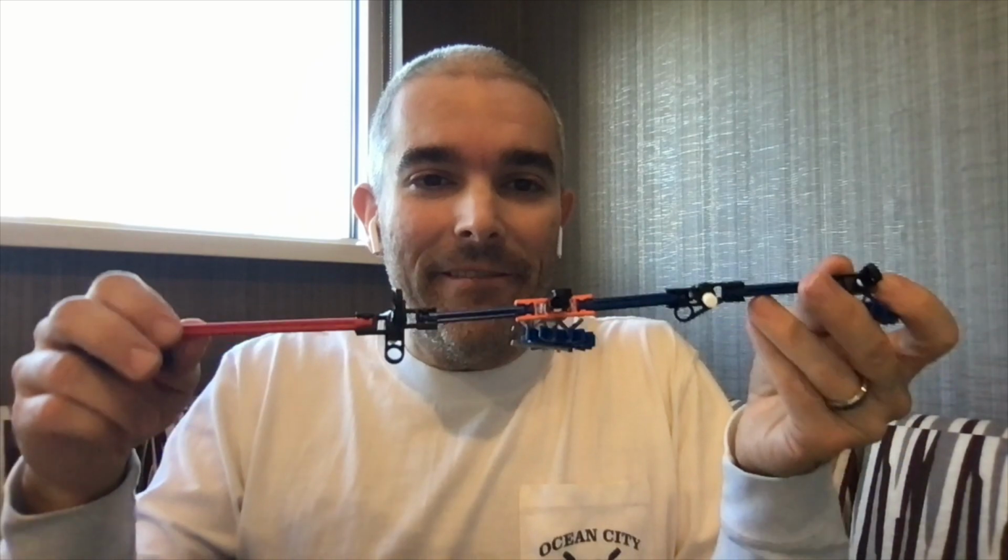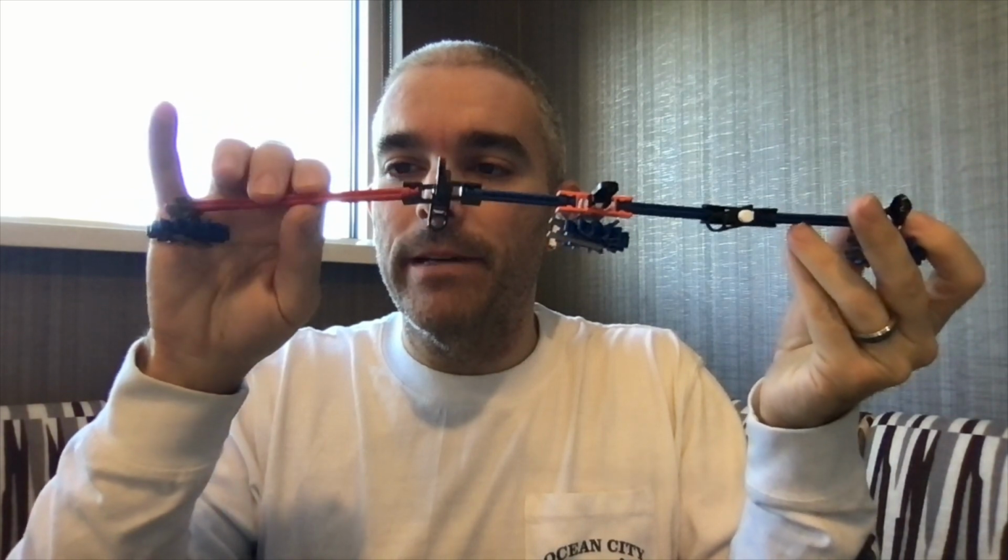All right, now we're going to look at the influence line for the moment at point F here, which is somewhere over here. So you have to imagine we put a hinge in right here, and then we're going to bend this down. Now, on this side, because this is the fixed end, I can't really bend this by putting in a rotation. So all that rotation is going to happen on just this side. And so that's going to rotate down. And then again, this passes through 0. And so we end up with a displaced shape that looks something like that, where this rotates down. 1 times 10 will give us a negative 10. If this is negative 10, this is positive 10. This is 0, 0. All right. I hope that makes sense.